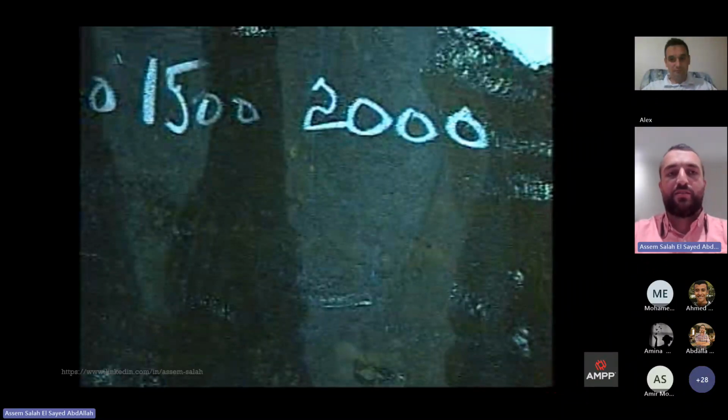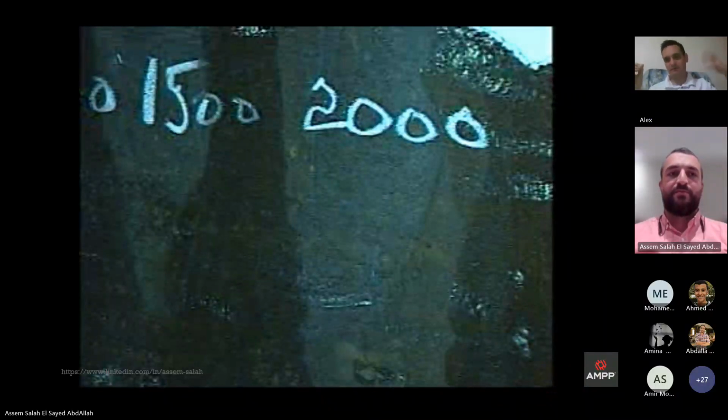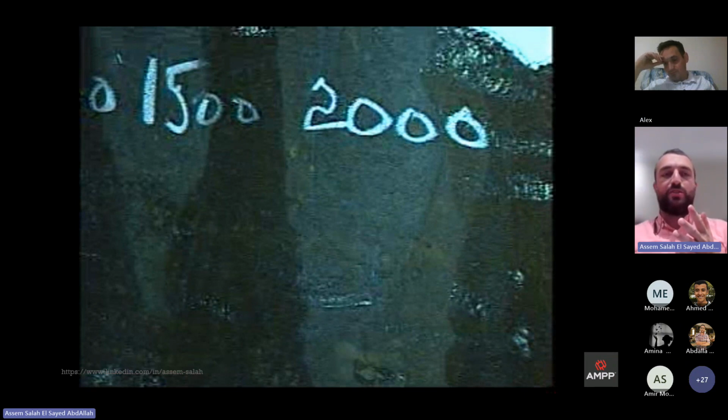I think you have some addition here, Mr. Alex. Yeah, I mean, removing the salt from the surface is a very important thing also in the industry, because salt impacts the adhesion. First of all, it is hygroscopic. It attracts salt from the ambient. And also, if you apply coating upon a surface which contains salt, you are not breaking the triangle of corrosion. You are just covering the surface with cathode, anode, and electrolyte. If you want to remove the electrolyte from the equation, you have to remove the salt from the surface, right?